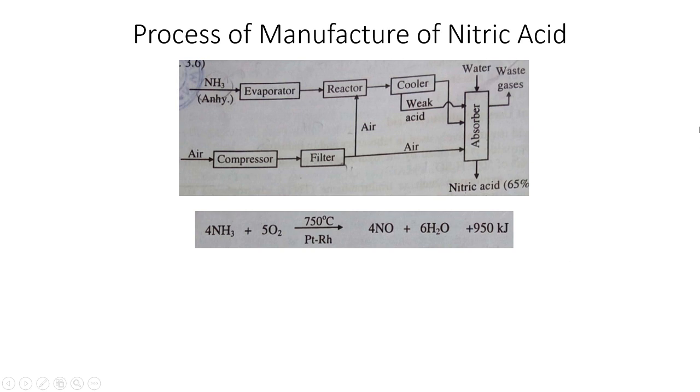Now the output of this reactor is hot gases. Which are those? Nitric oxide will come out, then nitrogen gas which is unreacted, or sometimes the ammonia, instead of getting oxidized to NO, gets oxidized to nitrogen. That is loss of hydrogen, which is also a sort of oxidation. So NO, N2 gas, O2 gas and steam come out of the converter; these are the output of the reactor. Now what happens with this gas?